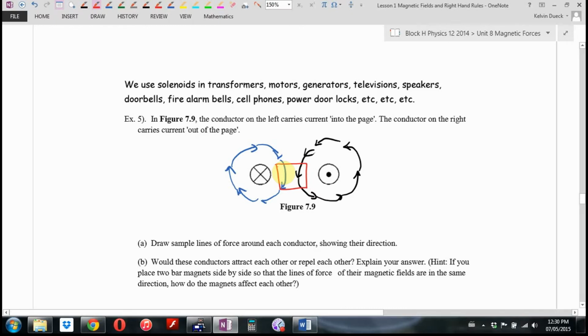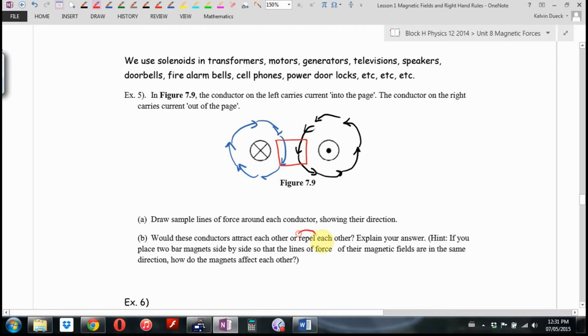And if you didn't have them stapled down, because that would happen over and over every time you turned it off and on, you could wear the ends of the wires out, cause a short, cause a loose circuit, cause a loose wire, fire bad. So they actually have to take this into account. Now again, for household circuits, because most of them are alternating current, it wouldn't make a difference because you'd have a net magnetic field oscillating, the net field's basically zero. But for a direct current, those wires would get pushed apart. So these would repel each other.